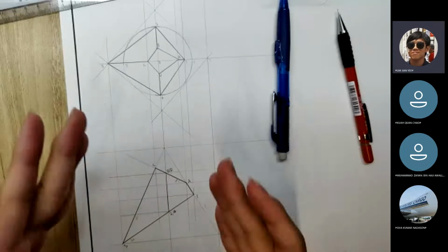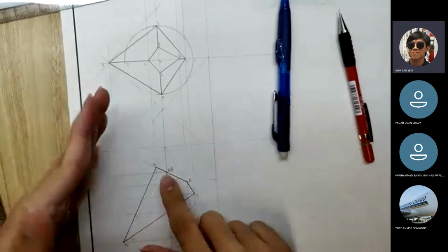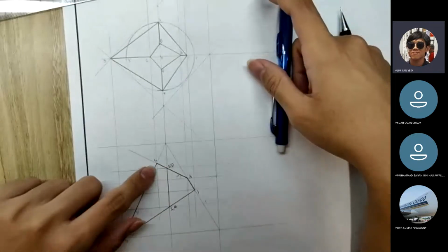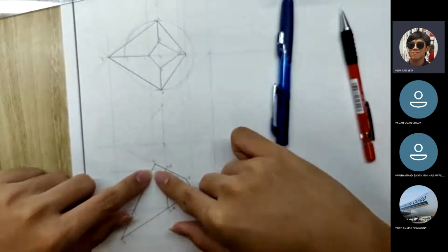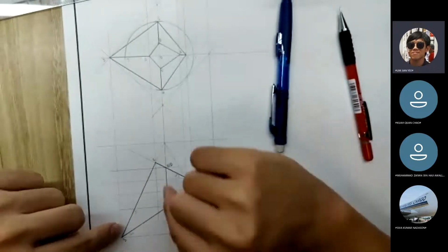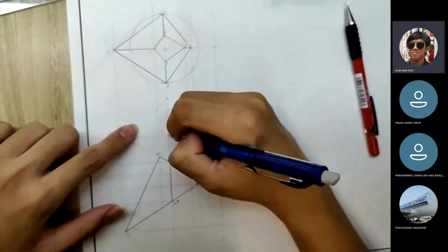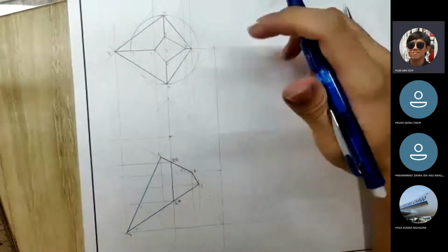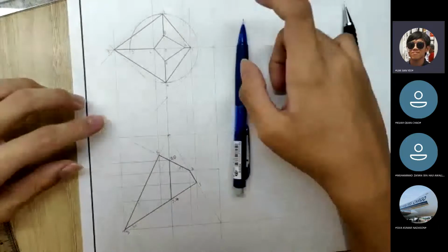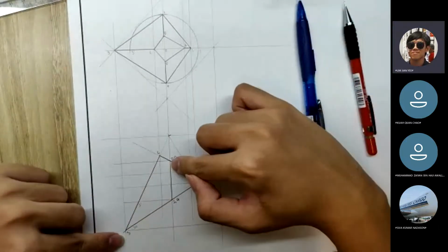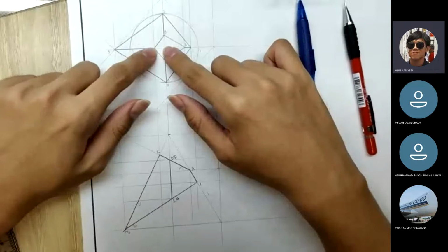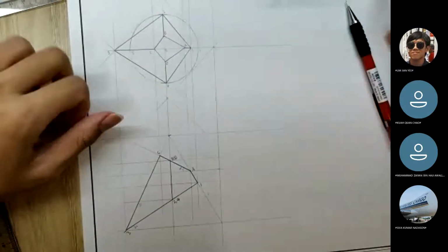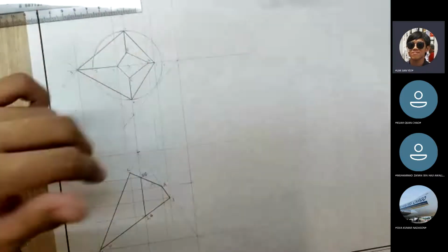There'll be a lot of triangles for the development. So when you have a triangle and you have like a 30-degree cut or 45-degree cut, link it to the edge of the thing, like here. If you look from this side, this entire line is a true length. So true lengths are very important. When you project it to a true length, you can bring it up and draw a circle, so you can find the distance between O and B, A. You use it a lot more in the future.